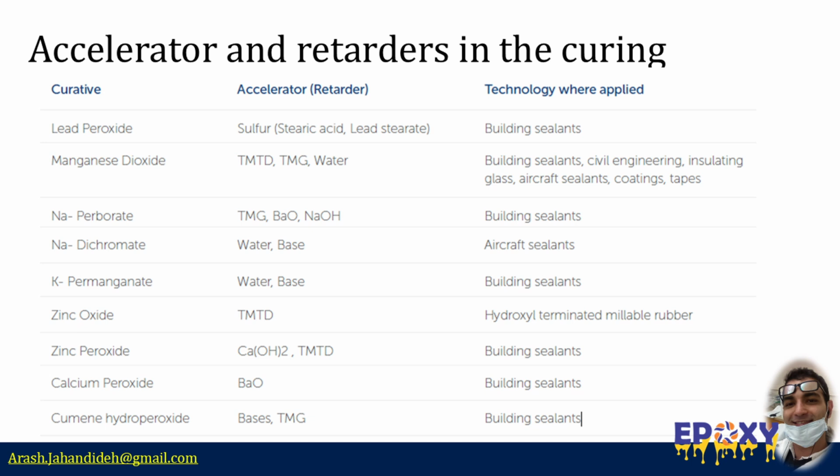For aircraft sealants, older chromate systems may include specialized organic accelerators for enhanced thermal resistance. On the other hand, removing trace moisture can significantly retard or even prevent curing. Therefore, water scavengers such as zeolites or barium oxide or BaO are often incorporated into the single component moisture activated systems to extend shelf life while maintaining reactivity upon exposure to atmospheric moisture.